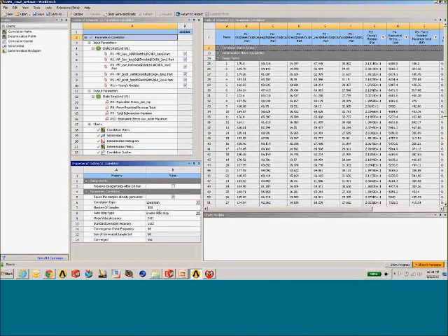But additionally, we'd like to say, all right, let's start out with, say, 100 samples. Now, the more samples you use, obviously, the more accurate your correlation is going to be. But even if I say 100 samples, it's not necessarily going to have to generate that because it's going to do some checking when I enable the auto stop. It's going to look at the standard deviation, and based on a convergence criteria on that standard deviation, is going to determine if it needs to continue to vary that particular parameter or if it can eliminate design points from that list. That's illustrated here. I requested 100 samples, and I received back a sample size of 60.